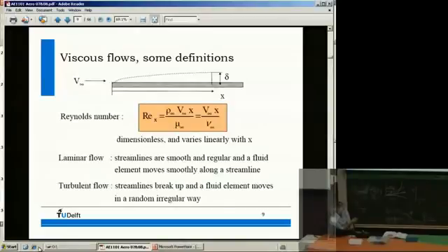And if you compare that to something large, like an aircraft, suppose it's still flying at the same speed as a fruit fly. An aircraft probably isn't, but an aircraft is 1,000, 10,000 times as large. So then your Reynolds number would be much larger, so you need much higher viscosity to get down to the same Reynolds number. So that's why I say a fruit fly flying through air has the same Reynolds number as an aircraft through really, really thick oil.